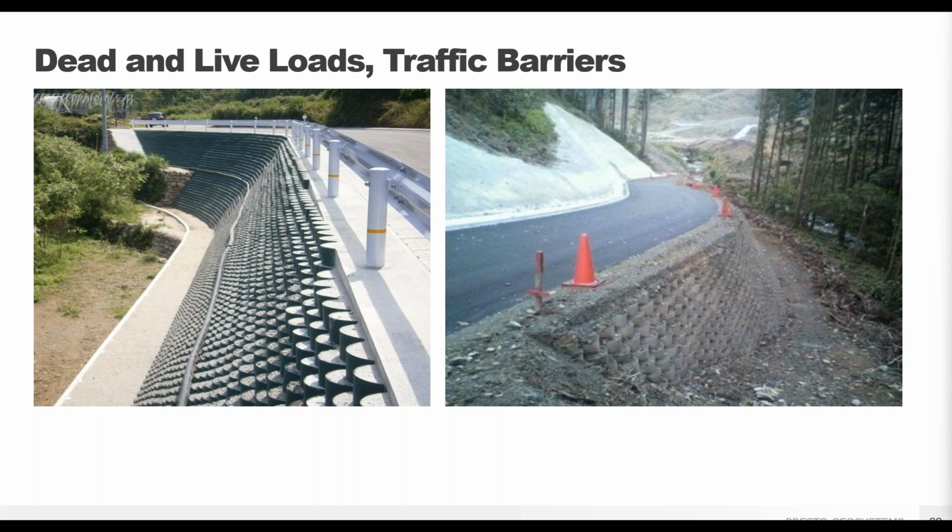When possible, these loads should be placed away from the edge of the wall or fascia. If not, the design will have to be robust enough to support and withstand the live and the dead loading. Having traffic barriers at the top of the wall will help keep the loads away from the front face of the wall system, which can also help with the design.